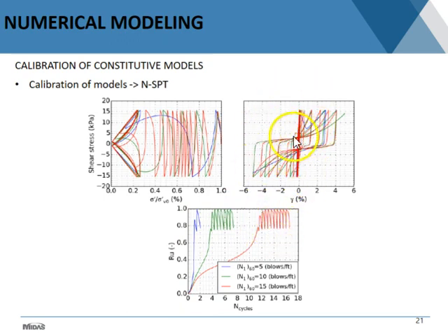Now, if you express that in terms of shear stress versus shear strain, you get loops that are of course different. The blue one is the weakest, or the soil that is most susceptible to liquefaction for this analysis, and you reach these banana loops rather easily.